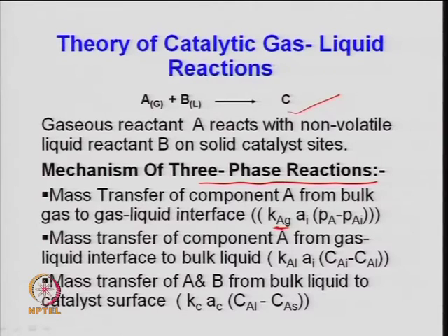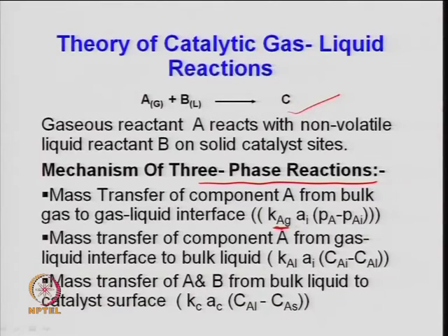In gas-liquid reactions, as you know, the interfacial area is very important. Same thing here, because it is a matter of the solubility of the gas in the liquid, governed by Henry's law and other experimental conditions. So, it is basically the interfacial area of the film times the partial pressure of gas A, P A, minus the partial pressure of gas A at the interface, P A I.